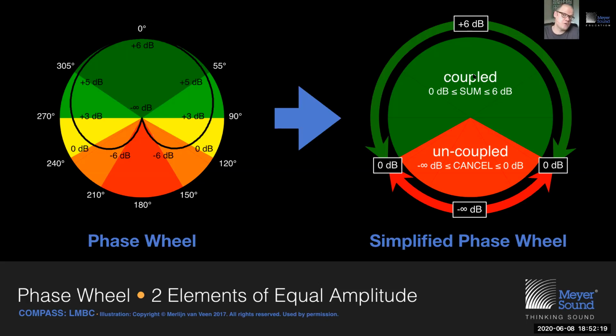And for 20,000 frequencies, these are 20,000 different times, because 1 kilohertz takes 1 millisecond to finish a single revolution. Therefore, 1/3 of a cycle is 0.33 milliseconds. Whereas 100 hertz takes 10 milliseconds to finish a single revolution, and therefore 1/3 of a cycle is 3.33 milliseconds. But the principle holds. 2 signals arriving within 1/3 of a wavelength, 1/3 of a cycle, 120 degrees are coupled and will add rather than subtract.